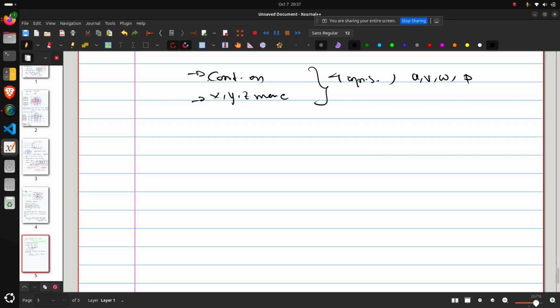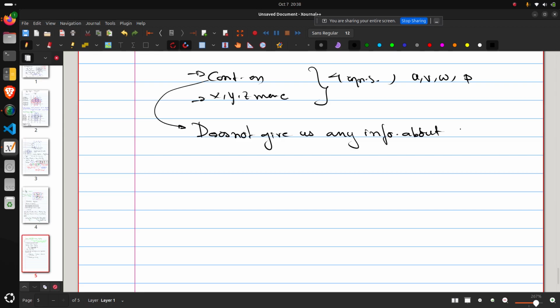But the issue is the continuity equation is not a transport equation. The continuity equation enforces the conservativeness in the fluid flow. It does not give us any information about the pressure field. Okay, so we cannot consider it as one of the equations that we can solve to get the 4 unknowns. So what do we do? We convert this continuity equation into a pressure correction equation.